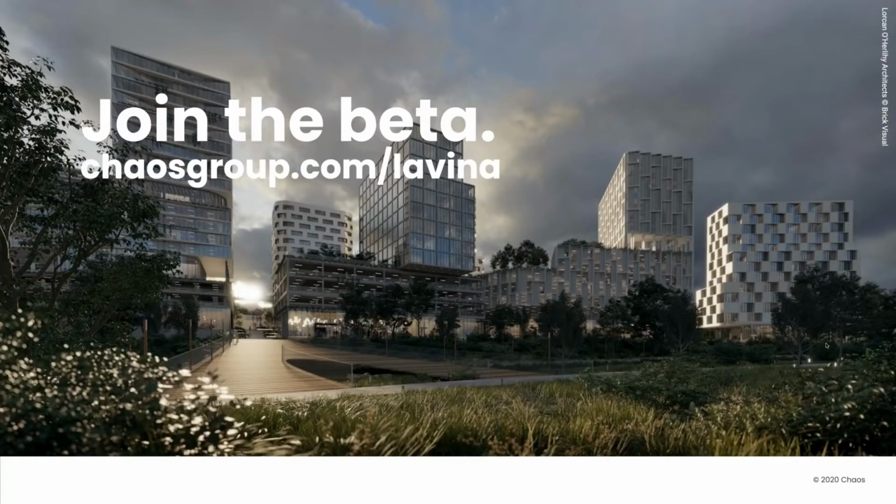So for example, if you have cars or people walking around and the trees moving around, this animation done in, let's say, 3ds Max for the sake of example, you bake this in the VRC and import it, and then you just find your cameras and make your shots in Lavina on the blue layer, the one on top of that. You can combine both the animations, but you cannot edit the original ones yet.